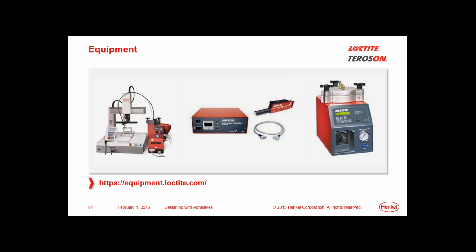I had mentioned that package size is an important consideration for your process. That goes along with dispensing equipment. There are many applications where manual dispensing is fully suitable for the application at hand because there is sufficient labor available. It's very easy to do. On the other hand, there's plenty of applications where a robot offers quality and precision and precise adhesive dispense and minimal waste because you have a controlled dispense onto a relatively more complex piece.